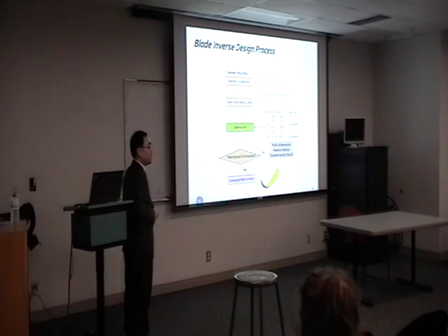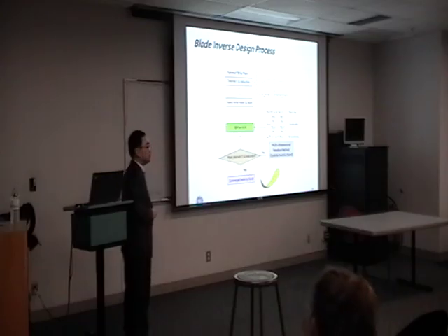Those are what I have discussed earlier. And then we check whether the calculated CL and axial induction meet the desired target or not. If not, we solve the multidimensional Newton method to update the blade chord and twist and rerun the BEM and BLM. So this process is repeated until we get the converged solution.